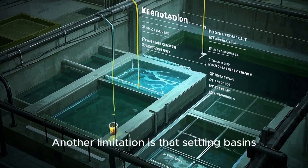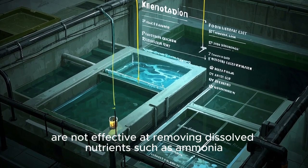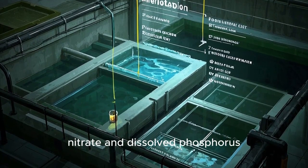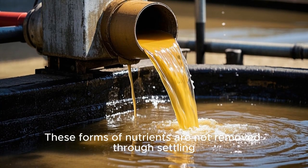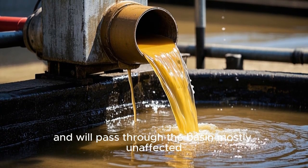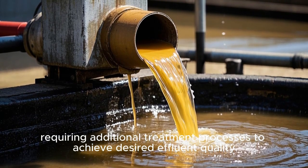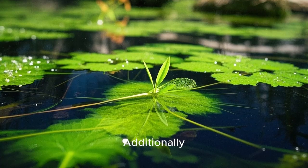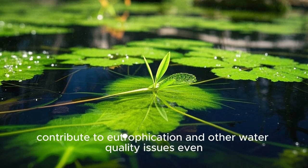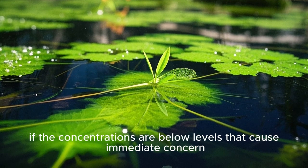Another limitation is that settling basins are not effective at removing dissolved nutrients such as ammonia, nitrate, and dissolved phosphorus. These forms of nutrients are not removed through settling and will pass through the basin mostly unaffected, requiring additional treatment processes to achieve desired effluent quality. Additionally, dissolved nutrients can still contribute to eutrophication and other water quality issues even if the concentrations are below levels that cause immediate concern.